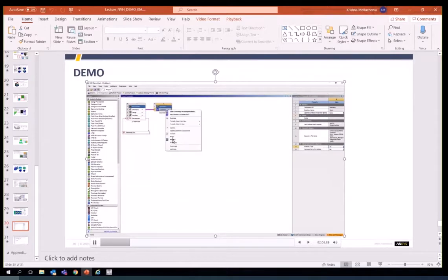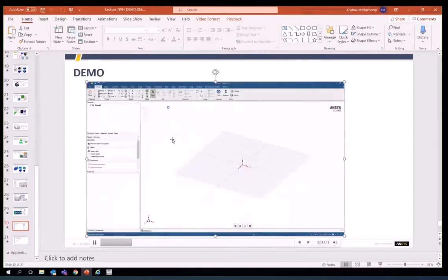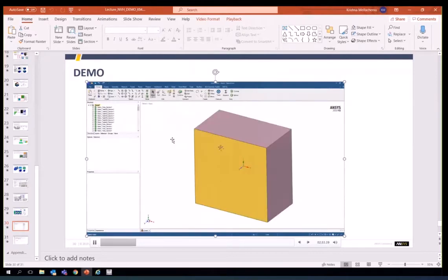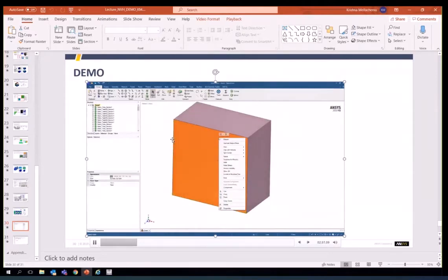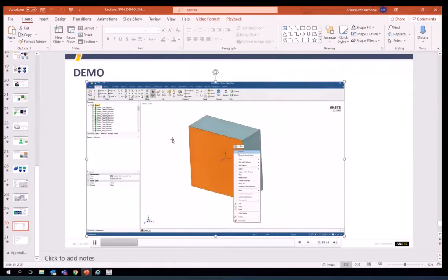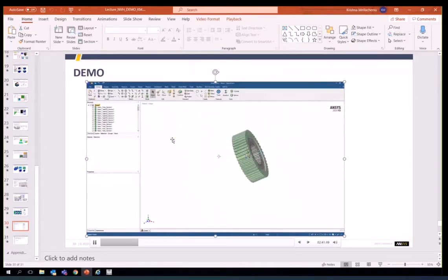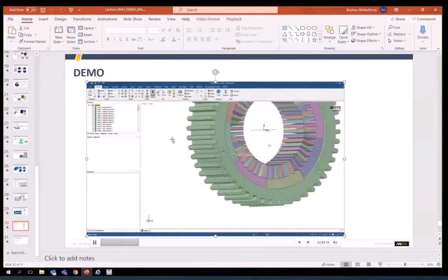So once we do that, we can change the geometry from 2D to 3D, and you'll see how the geometry looks within SpaceClaim. So this is SpaceClaim, the ANSYS CAD tool. It's a direct modeling tool that we can use to further improve the geometry. So this is the air box around that I'm hiding, and then this is the motor, the stator part with the teeth.